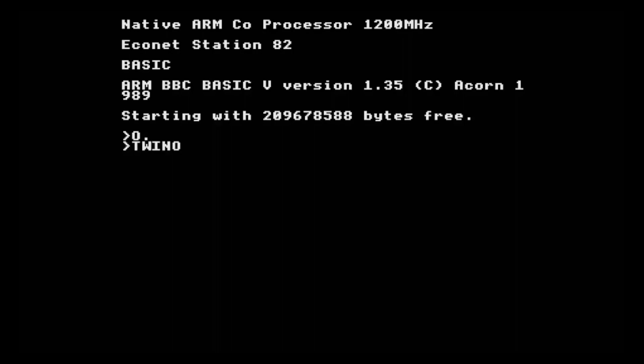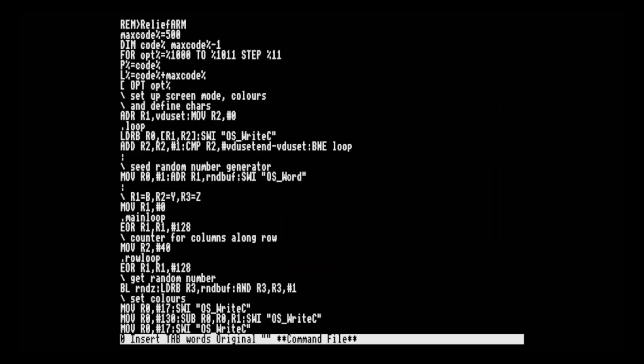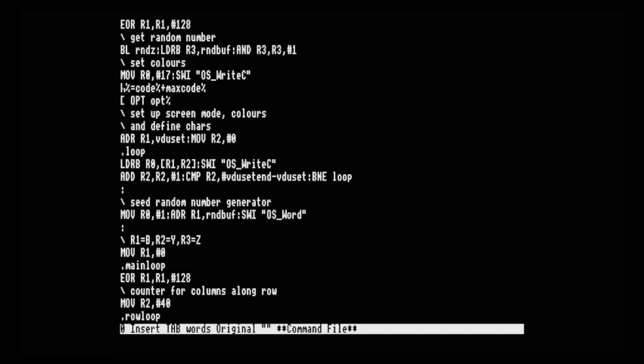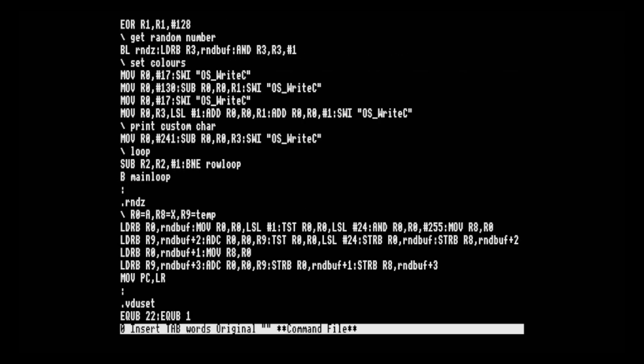I go back into the program, and the reason why that isn't working is to do with this final subtract that we just converted. So if I move down to this subtract in the loop, this is because apart from instructions that explicitly do only tests and comparisons like CMP and TST, all the other instructions don't affect the condition codes like the Z bit, the Z condition flag to say that two numbers are equal or things like that, unless you explicitly ask them to.